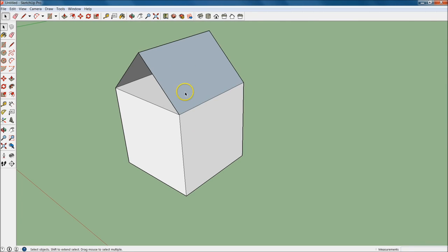What we're going to do is we're going to undo that real quick with Control Z, and we're going to do the push-pull tool right there. And as we're pulling back like this, you'll see that it goes blue, right? I want you to just hit Control. Did you see that? I just hit Control. Now on the Mac it'll be Command. If not, somebody comment and say it's not. But you're just going to pull it back and then drop it on that point right there.